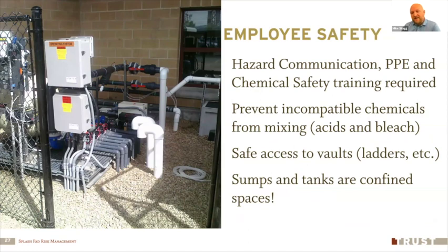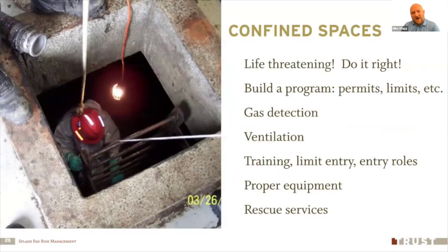Okay, make sure there's safe access to vaults like ladders. Sumps and tanks are confined spaces. Okay, your holding tank is a confined space. It needs to be marked that it's a confined space. Okay. Needs to be marked. This is danger, confined space, no entry, no authorized entry. Okay, you need to make sure you're marking these things. Those confined spaces are life-threatening. You got to make sure you do it right.